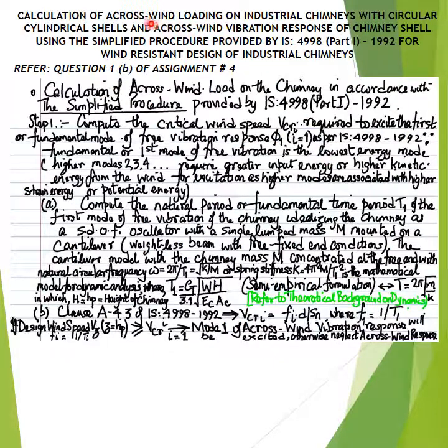Continuing our discussion on the structural analysis and structural design of industrial chimneys subjected to wind loading, as mentioned earlier, the wind exerts an along wind force as well as a crosswind force due to the drag and lift that are induced on any single stationary bluff body, obstructing a streamlined flow of fluid based on the first principles of fluid mechanics.